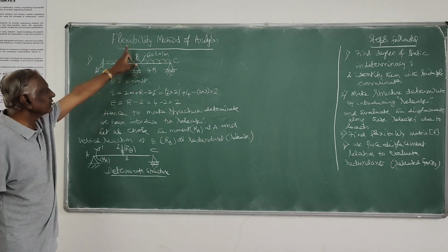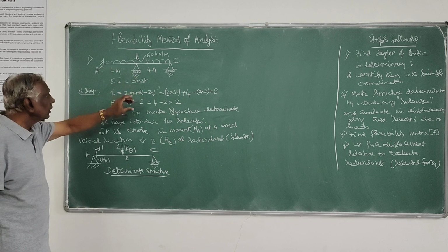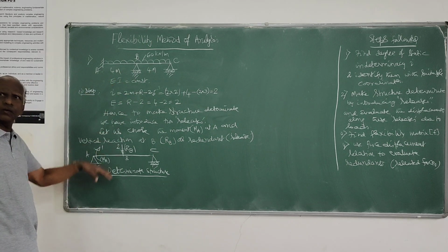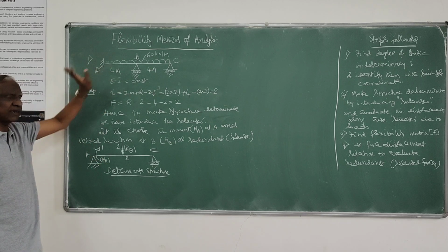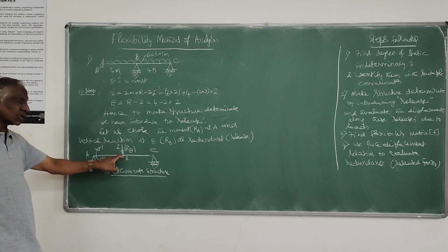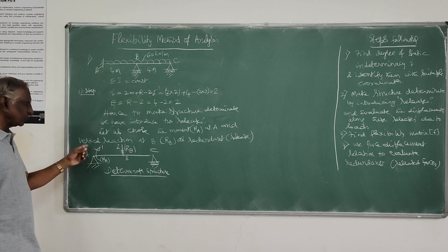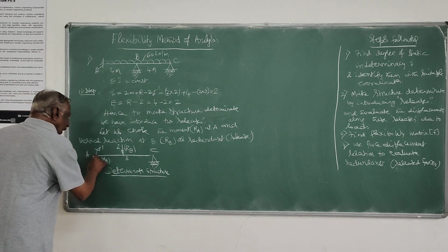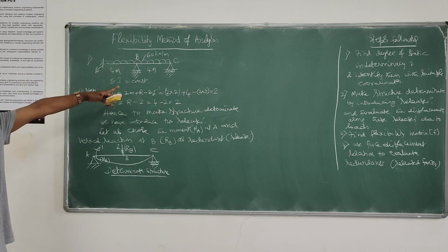Similarly, here it was not allowed to move up or down because there was a roller support. Now I have removed that. Now it is going to move in the vertical direction, either up or down, depending upon the load. So these are called the inconsistencies in the deformations. One is rotation, the other translation. Those two I have to evaluate for the given loading conditions.